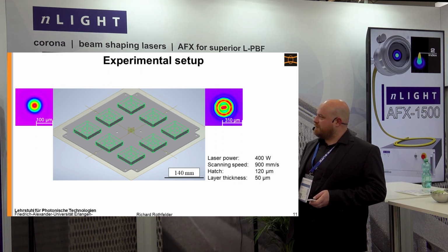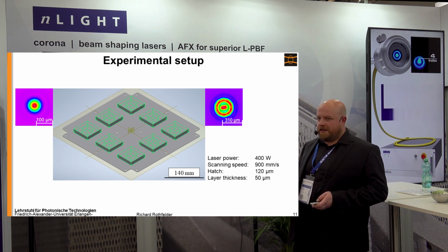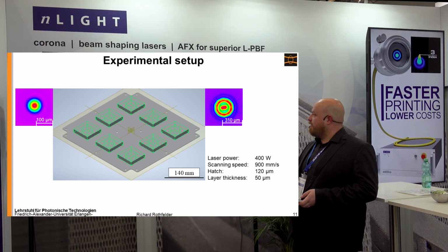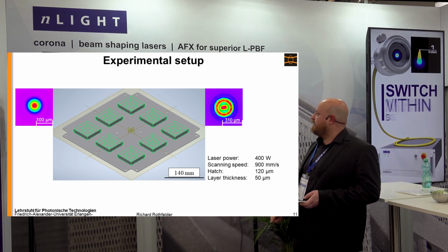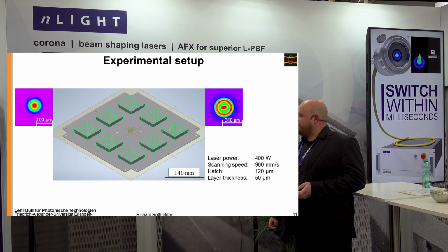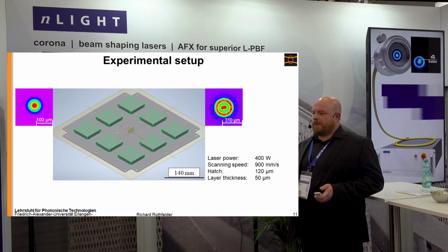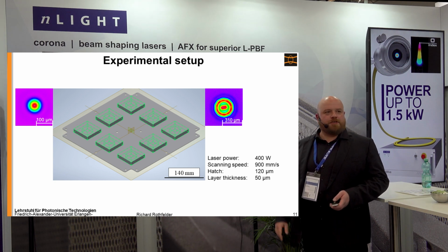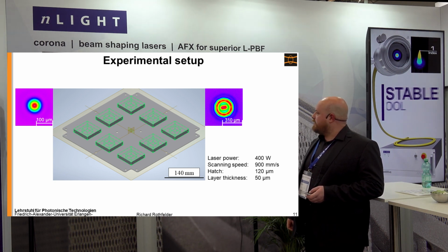And afterwards, by the cross sections, we will be able to find these tungsten particles and check in dependency of our used beam shapes, the Gaussian beam and the ring point beam profile, which creates the most spatter, and how far do the spatter travel during the scanning process.